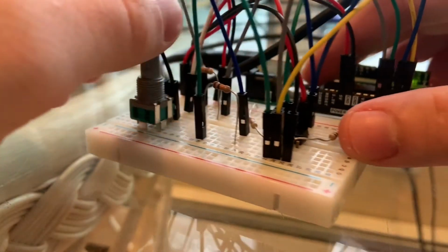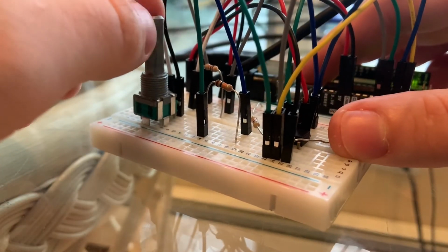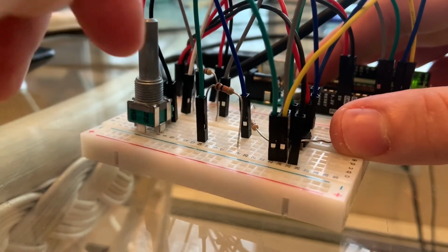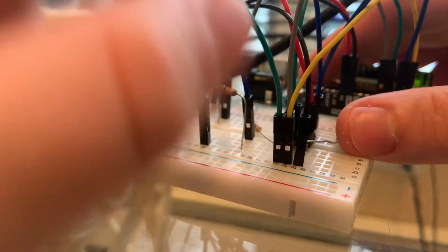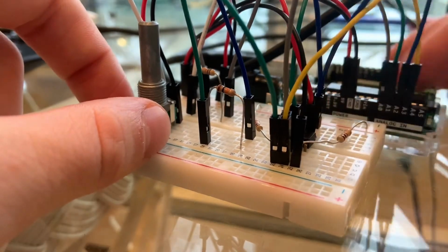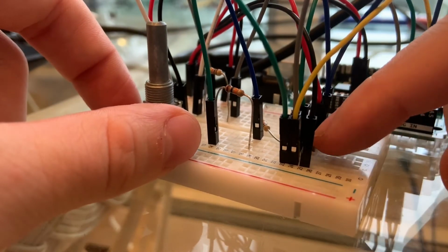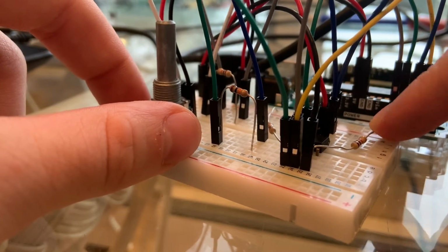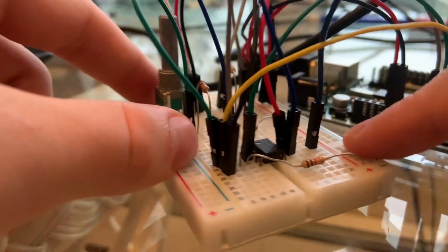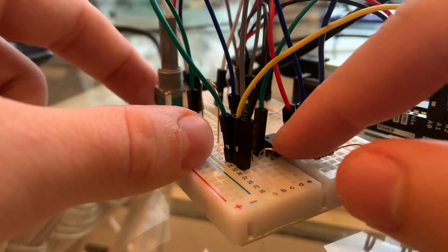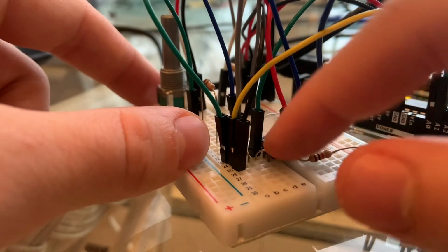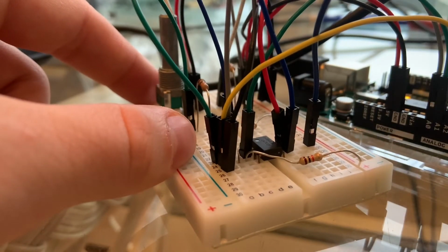All right, so now we're going to be looking at the circuit for exercise 3. We have this potentiometer, which is supplying our V in, goes straight through the resistor and then straight into V minus. From V minus, it goes out and then through another resistor, which then goes straight to V out here. And then for V plus, we need it to be exactly 2.5 volts. So we used 2 resistors here as a voltage divider. And then this yellow wire is reading that, and it maintains 2.5 volts.